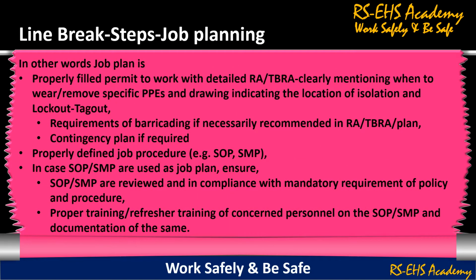Further to the line break step, job planning. In other words, the job plan is a properly filled permit to work with detailed risk assessment or task-based risk assessment, clearly mentioning when to wear or when to remove specific PPEs, and a drawing indicating the location of isolation and lockout tagout. Requirements of barricading if necessary, as recommended in RA, TBRA or plan, and contingency plan if required. Properly defined job procedure, for example SOP, SMP.